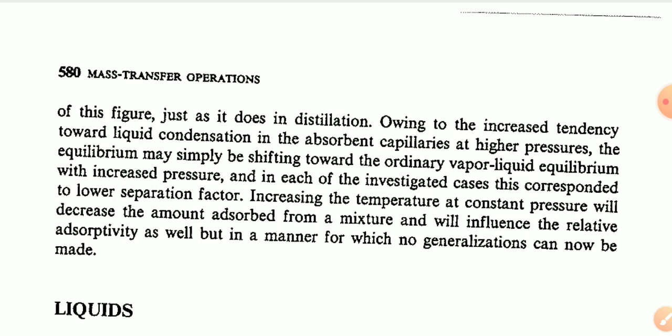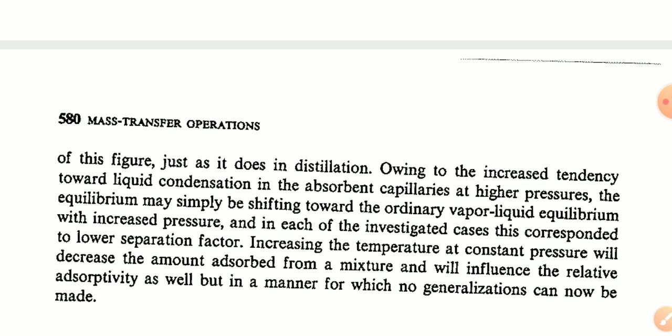Just as in the distillation part, owing to the increasing tendency toward liquid concentration in the adsorbent capillaries at higher pressure, the equilibrium may simply be shifting towards the ordinary vapor-liquid equilibrium, and with increased pressure, as you increase the pressure, the pressure of that will also increase. In each of the investigated cases this corresponds to a lower separation factor. Increasing the temperature at constant pressure will decrease the amount adsorbed from a mixture and will influence the relative adsorptivity as well, but in a manner for which no generalizations can now be made.